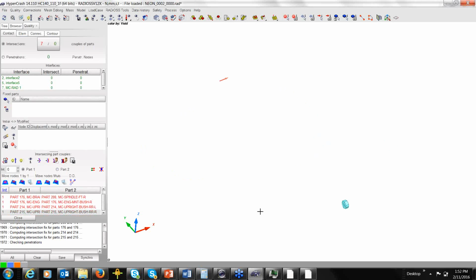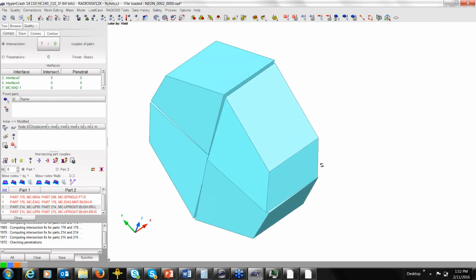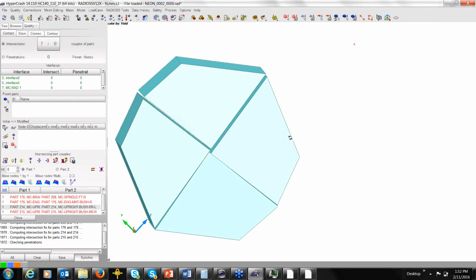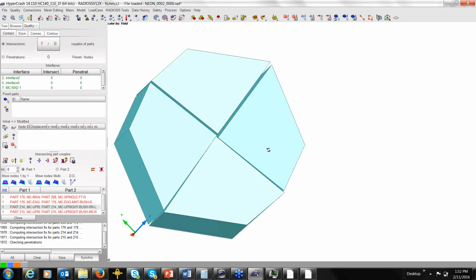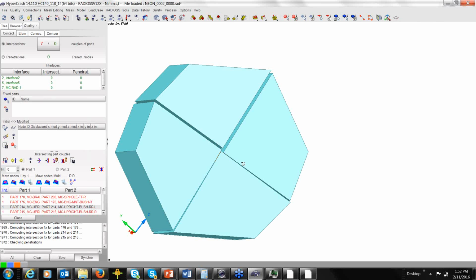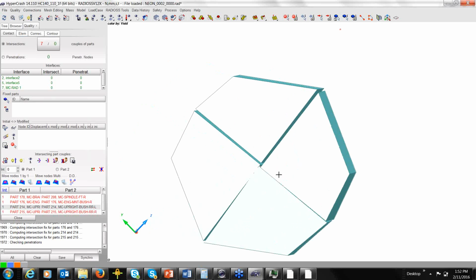So when I have intersection before starting, my contact will not be working, because contact is to avoid two parts crossing each other. Before the analysis, they have already crossed. So if I want to monitor the contact force between those two pieces in this area, the contact is already violated. I can't have the correct contact force. So intersection is not acceptable in your analysis.